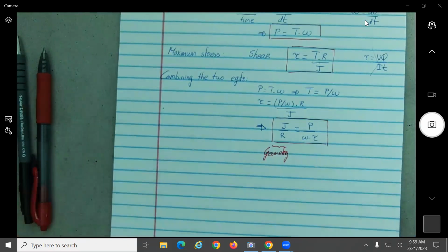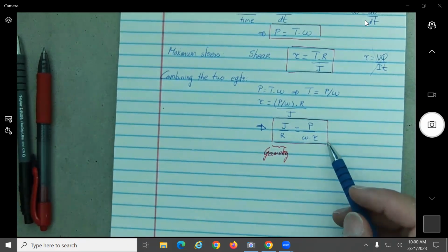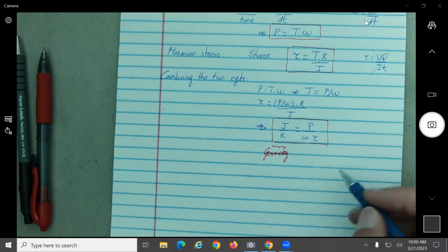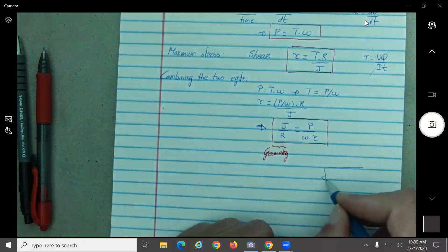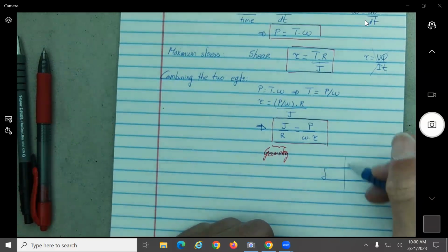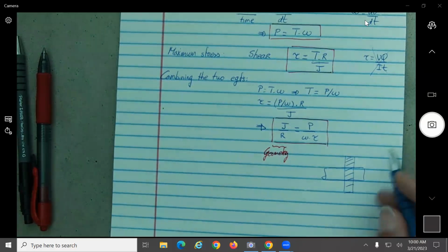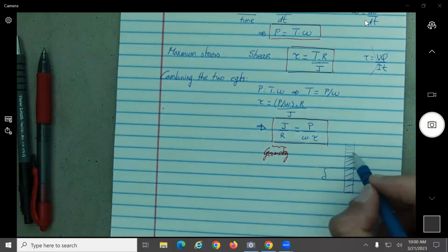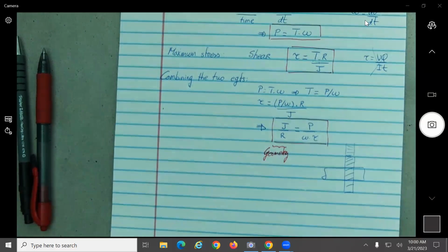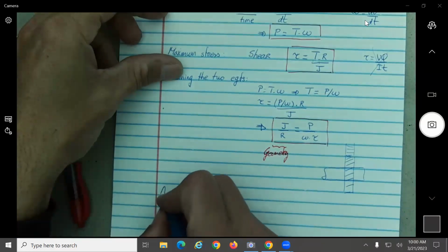I think I discussed at the end that this is a problem where most people will start over here when designing a shaft. But what is important when you design a shaft? Let's say you have a shaft with different gears attached to it. What is important between the contact of the shaft and the gear is that there is no slip, no? So when this is in contact with another shaft, it is not going to start slipping. So basically, what we need to define is the angle of twist.